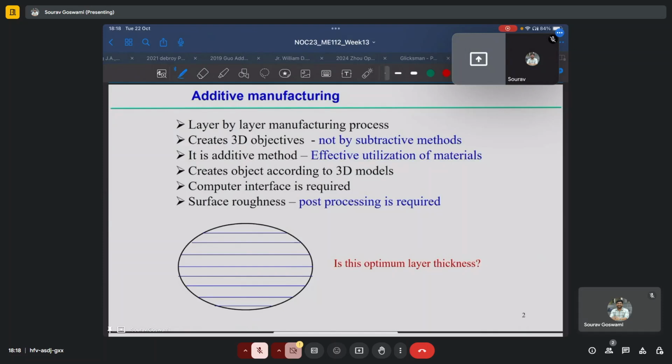Apart from this, subtractive steps are also needed in the post-processing stage of most additive processes, and the reasons can be varied. So you may require a subtractive step to achieve the desired surface roughness, because as we know, typically the as finished surface roughness for most AM processes would be pretty coarse and not really suitable for any end application.